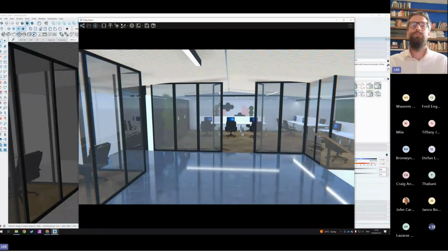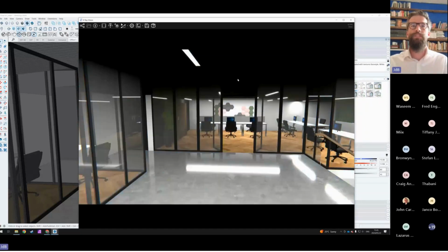So let's hide that information menu. Recollecting that down the staircase, the opening to the building is on our right-hand side, the sun will have an impact on this upstairs space. So I'm going to press the letter X and move my mouse from left to right, so that you can start seeing the differences as the sun rotates through the space. We're just going to move the mouse up and down so that we get that afternoon look and feel. You can see it's starting to get darker, and now the sun sets and it's basically evening.